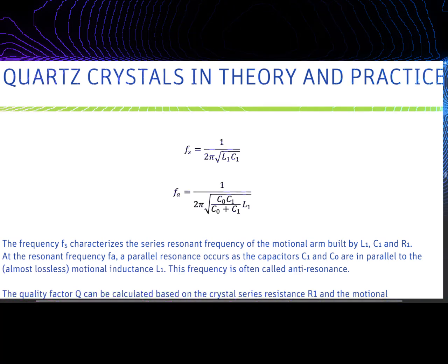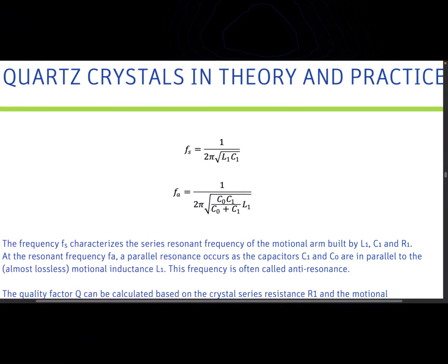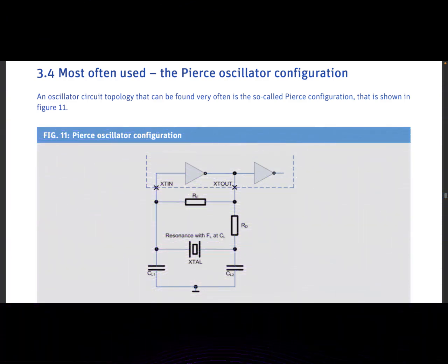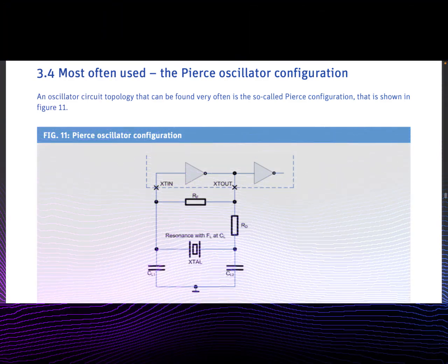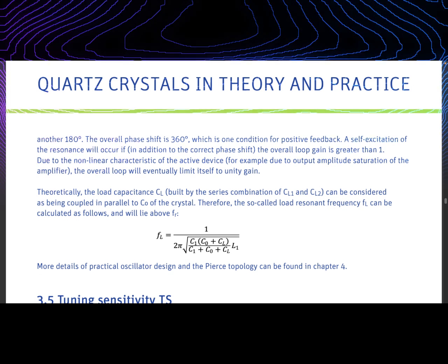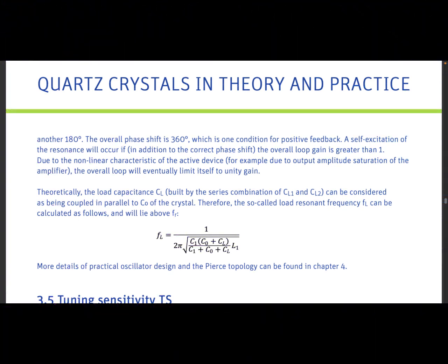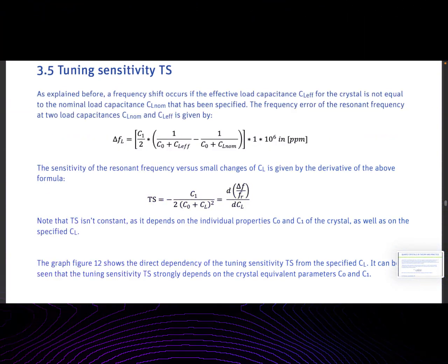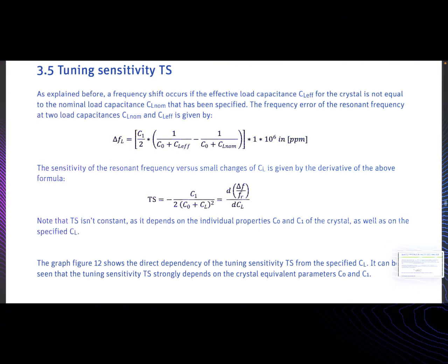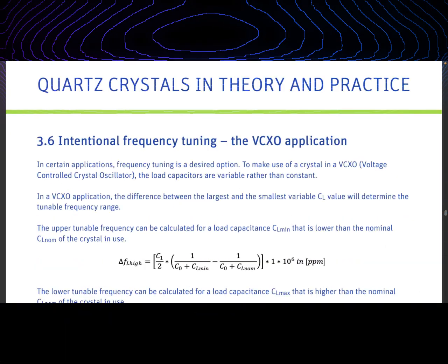In other cases, an off-the-shelf crystal oscillator module provides a simple solution. These are also available with higher accuracy and stability than integrated oscillators. If better temperature stability is required, then temperature-compensated oscillators are also available.